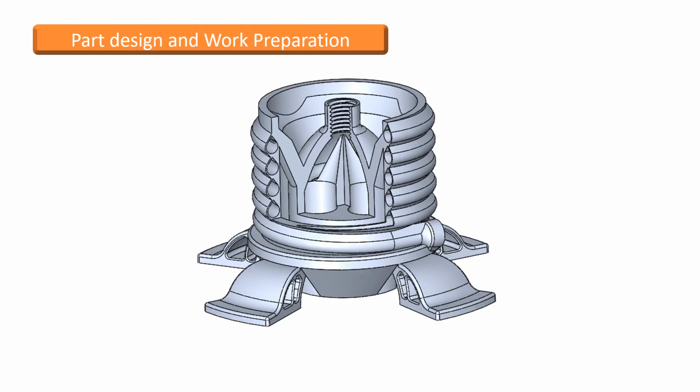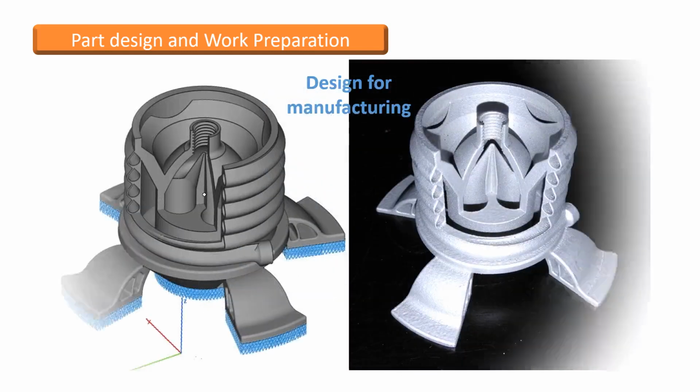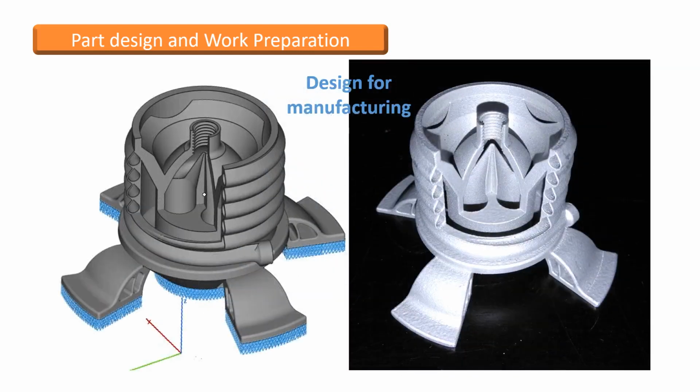That is, the assembly can be compacted into one part. Also, different functionalities can be implemented in the same part. There is, for example, cooling channels, a nozzle structure, and the operation of the structure as part of the frame structure. There is no need for support structures. If a part is removed from the platform using wire EDM, its bottom also becomes smooth and it does not need any other post-processing.